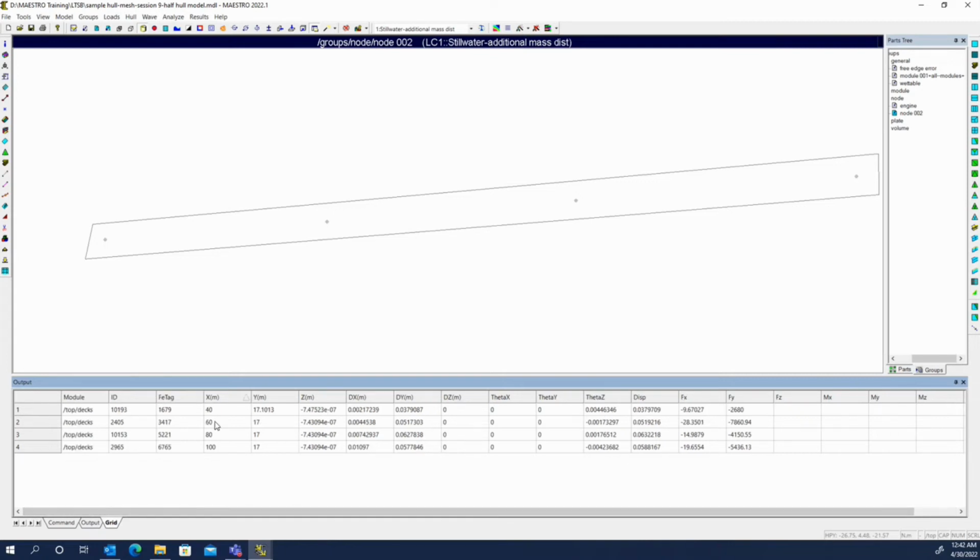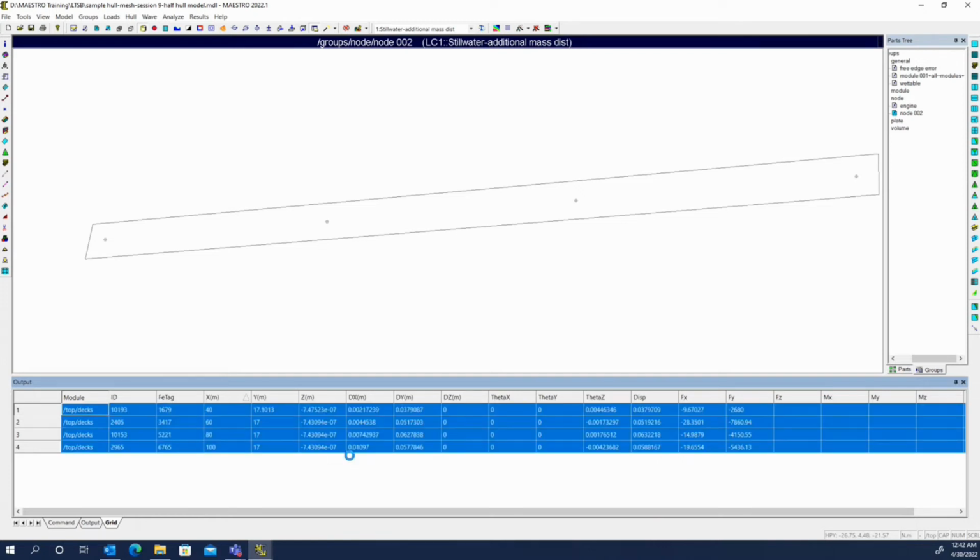And in this grid view, you can copy this information out, and if I hit Control A to select all, you can grab everything and then just right click and say copy. The other thing you can do, and I think we went over this once before, was in this particular view, if you wanted to cut and paste this into a spreadsheet, well, it would be nice to have those column headers in there. So what you can do is use the right click on one of the column headers and say change fixed rows and make the number of fixed rows 0.